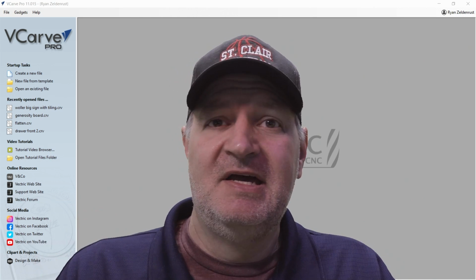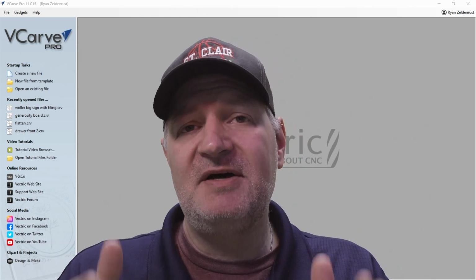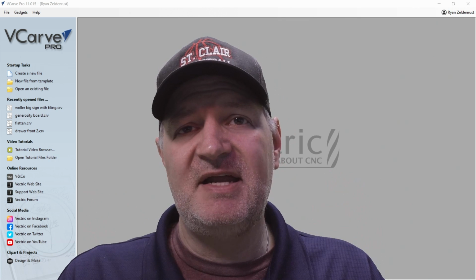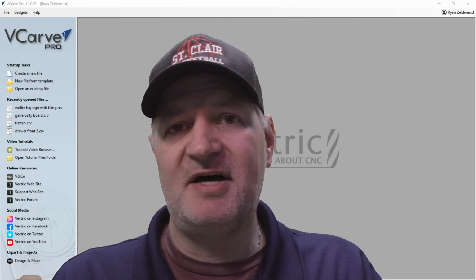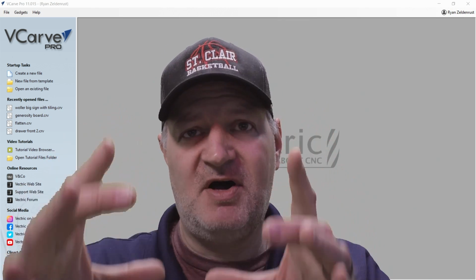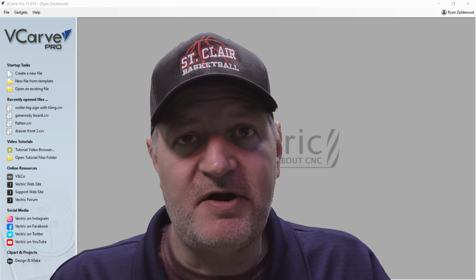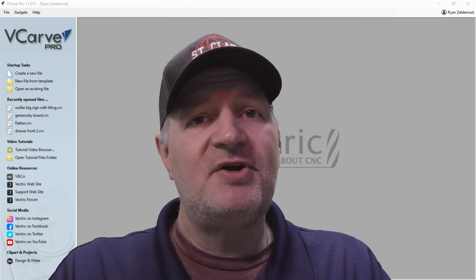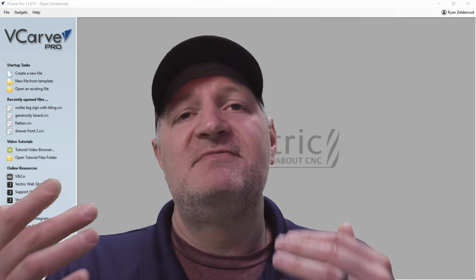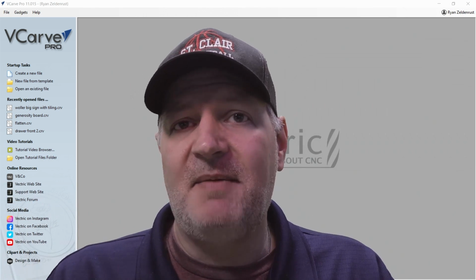But fortunately, Vectric has a tiling feature that allows you to take your workpiece and slide it up and down the y-axis or across the x-axis, or even to make small sections that you can put together later. So I'm going to show you how I used that feature to make this sign step by step.